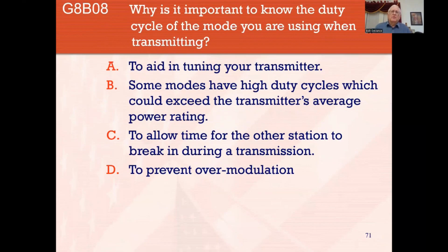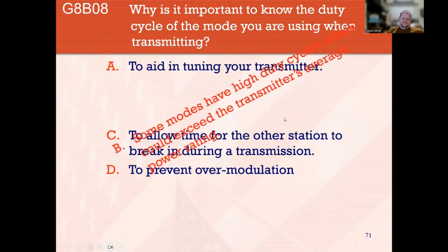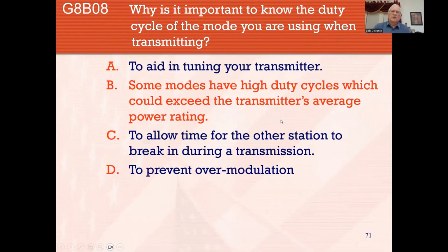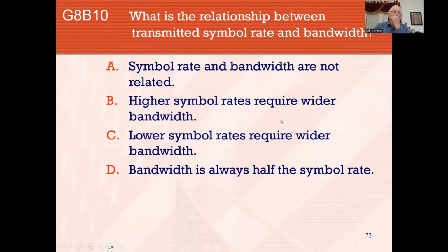Why is it important to know the duty cycle of the mode you're using when you're transmitting? We don't want to break the radio, do we? B. Do you agree? B. Yep. Don't want to exceed our transmitter's rating and blow it up.